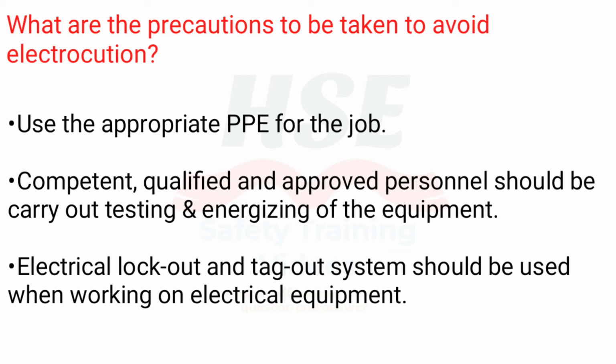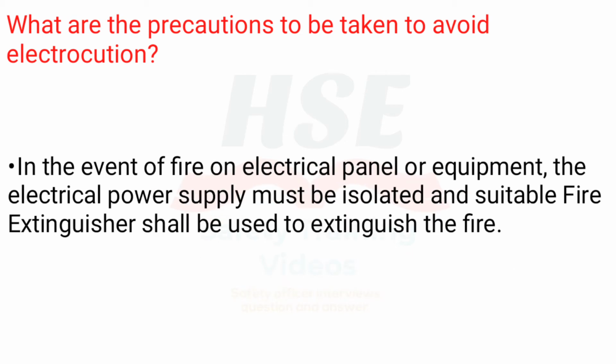Competent, qualified and approved personnel should carry out testing and energizing of the equipment. Electrical lockout and tag-out system should be used when working on electrical equipment. In the event of fire on an electrical panel or equipment, the electrical power supply must be isolated and a suitable fire extinguisher shall be used to extinguish the fire.